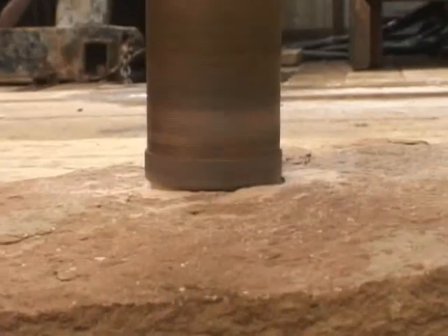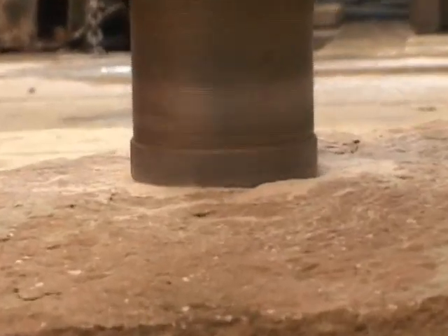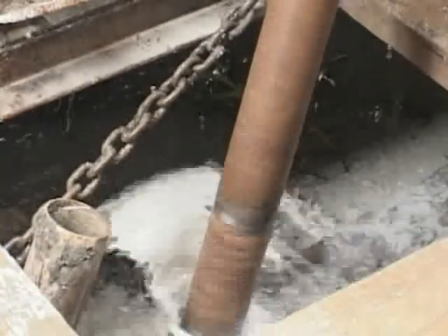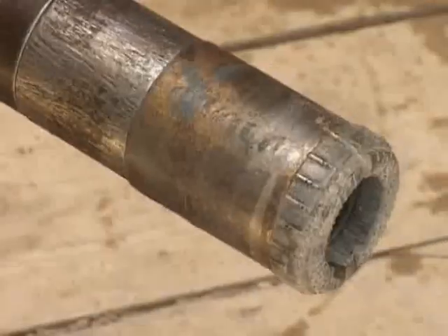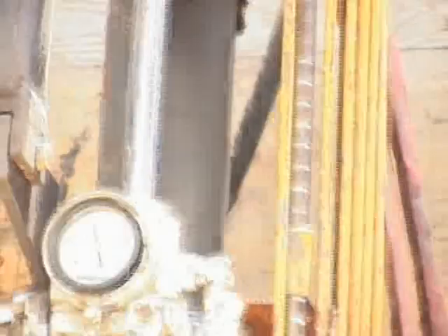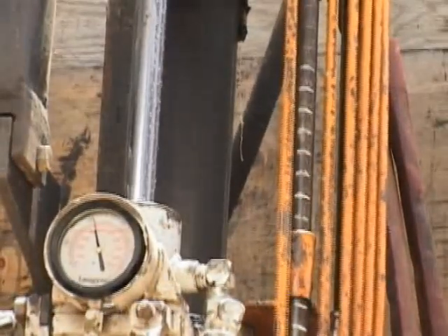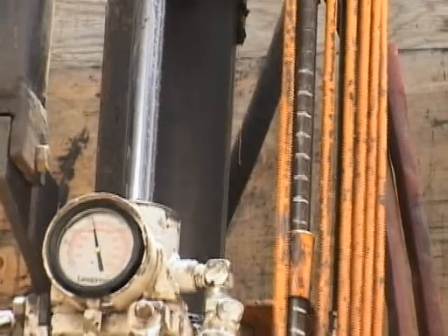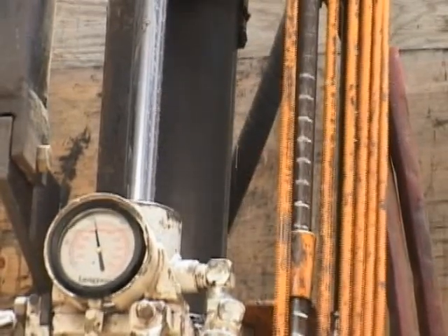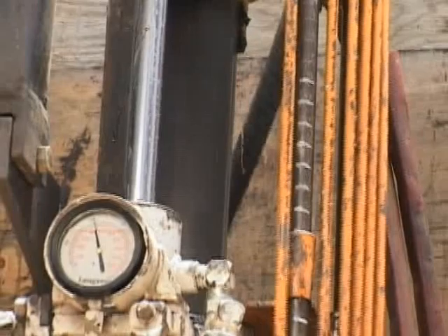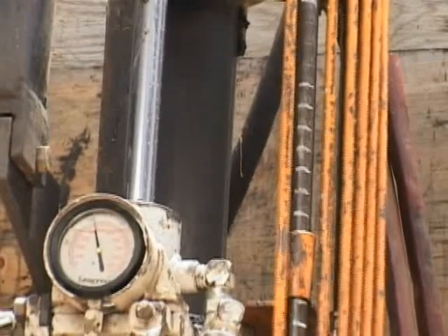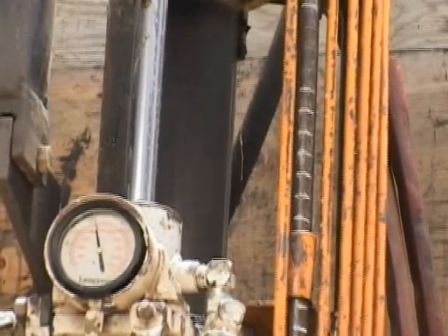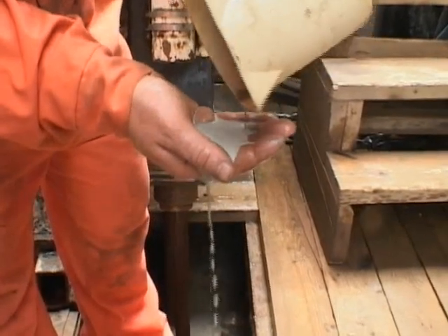The same cutting action is used for advancing the hole and the casing. This rotary abrasive action is achieved through high rotation speeds and pull down or thrust forces to enable the diamonds in the bit to wear away the rock. This results in relatively slow penetration rates as compared to other drilling systems, and very fine cuttings.